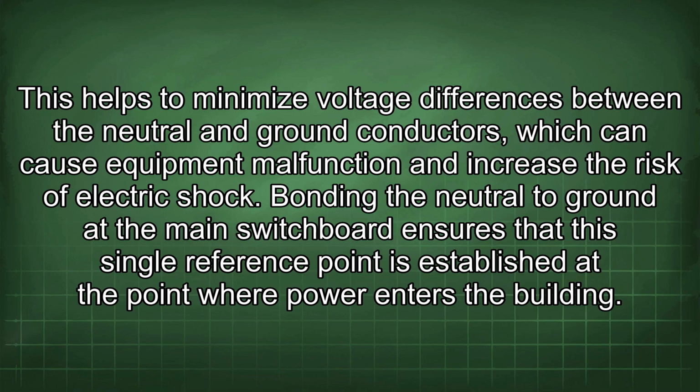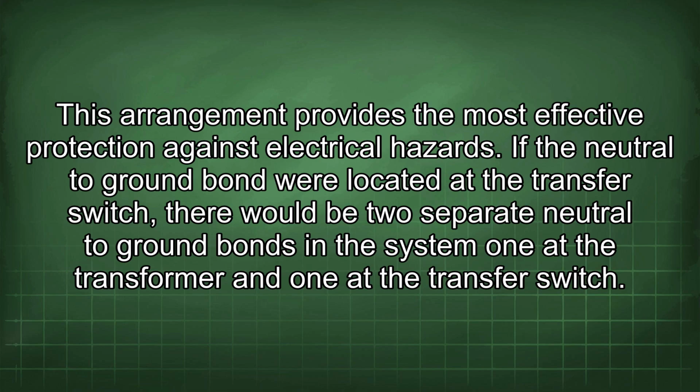Bonding the neutral to ground at the main switchboard ensures that this single reference point is established at the point where power enters the building. This arrangement provides the most effective protection against electrical hazards.